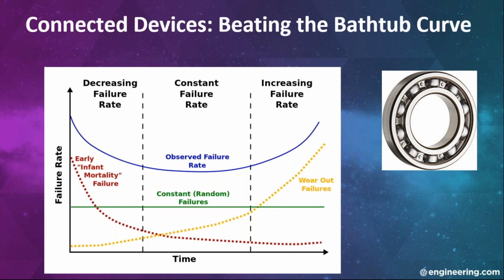Now, the low point in that graph, the blue line, represents the time in the service life of the product with the lowest probability of a service failure. But statistics like these are generated by measuring the incidence of failures over time. So this is post-mortem analysis made after in-service failures, and it's not predictive. Could that blue curve be extrapolated from information aggregated by the bearing before it causes a costly failure?